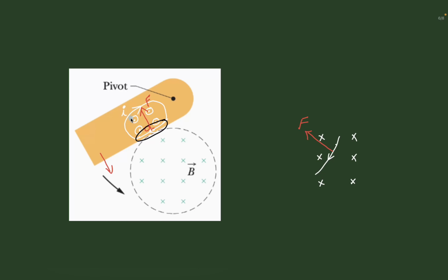So the eddy current that is produced is going to experience some force, and the mechanical energy that this has is being converted into eddy currents, and those eddy currents are going to generate some heat. That means by the time the sheet comes to rest after making some oscillations, all the mechanical energy being lost by the oscillating system will convert into heat because of the eddy currents that are developed in the sheet.